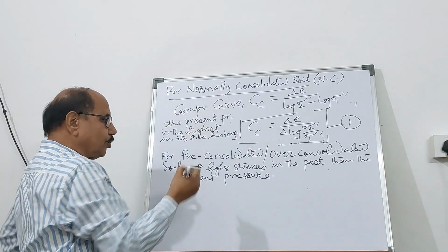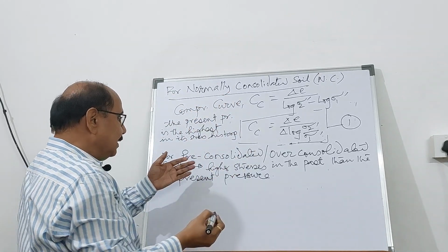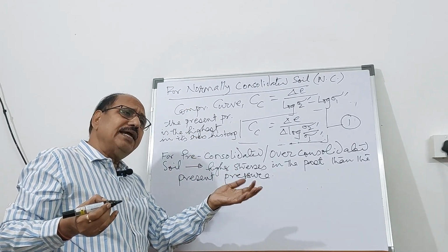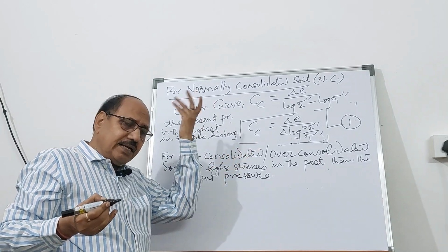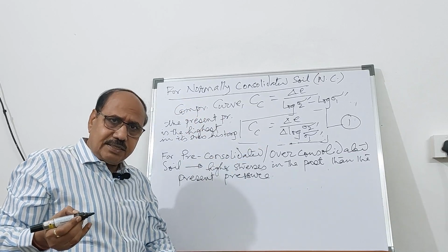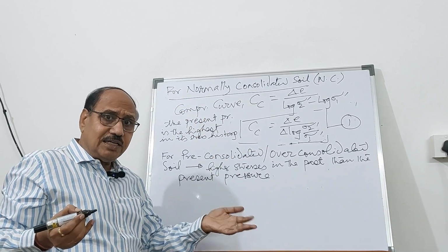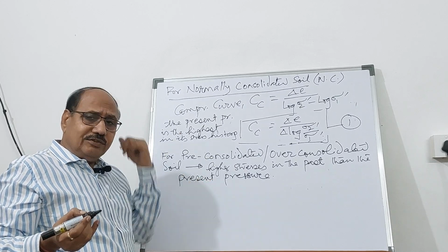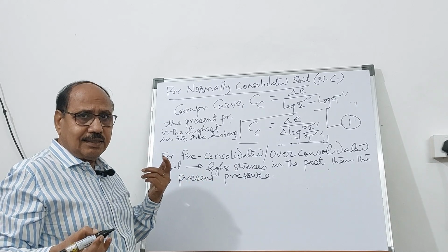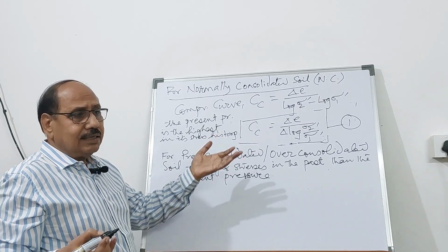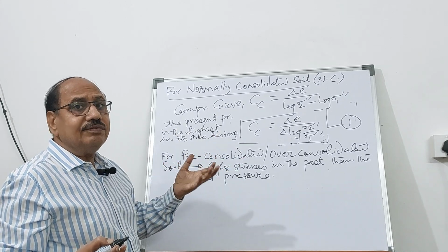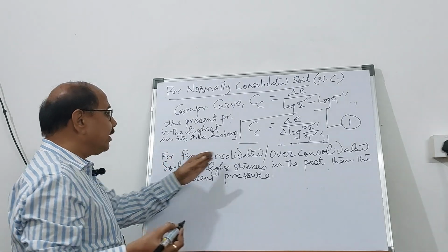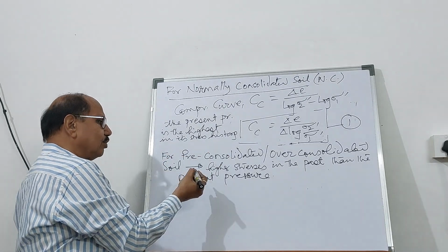Then it is normally consolidated. But here, as I told you, if there was any reason, whether there was a monument which is not existing today, say today the Taj Mahal is there, after a few centuries, if it is not there, then that soil will behave differently. That clay will behave differently. It will behave like pre-consolidated or over-consolidated soil.